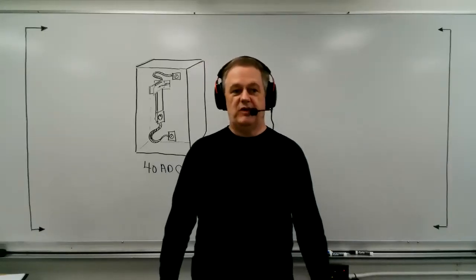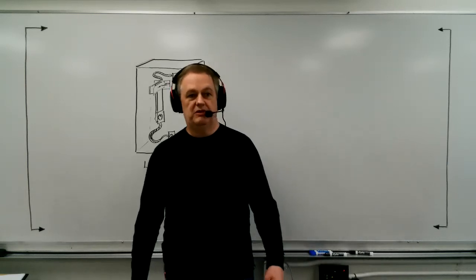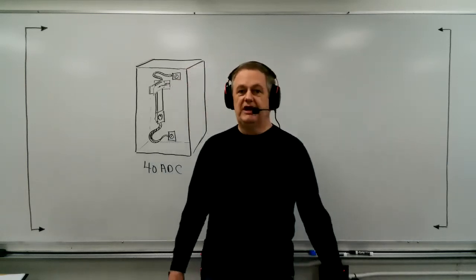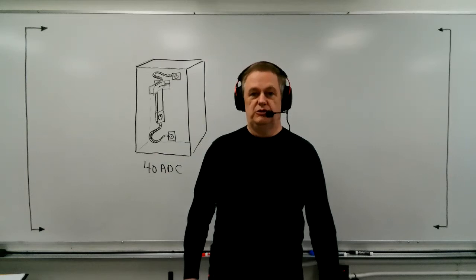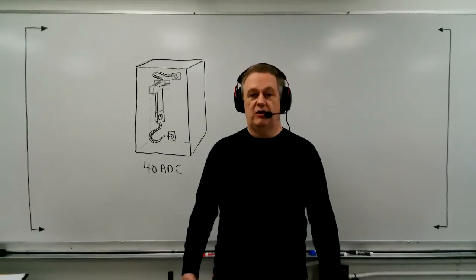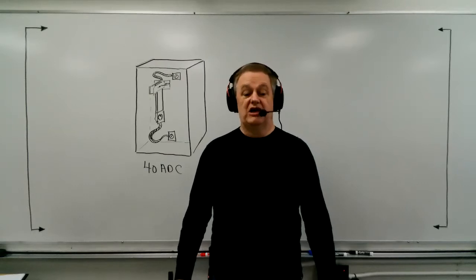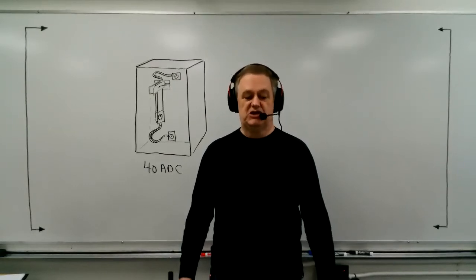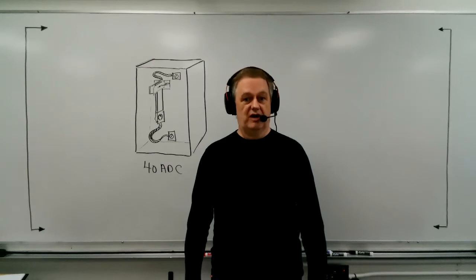Now, DC equipment, so the equipment, switches, and contactors required to handle DC loads, turn them on, turn them off, have always been very large in size, and that's because DC current is not easy to interrupt.